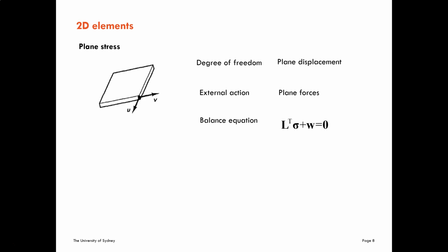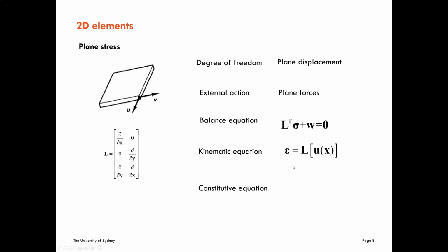And the balance equations are written like this, where this is the differential operator. The kinematic equations are the relation between the displacement vector, that is the u-v vector, and the strain, taking the derivatives using this L operator. And the constitutive equations are the relations between the stress and the strain. In our case, it is this D matrix, where E is the Young modulus and nu is the Poisson ratio. These are the governing equations of the plane stress element.